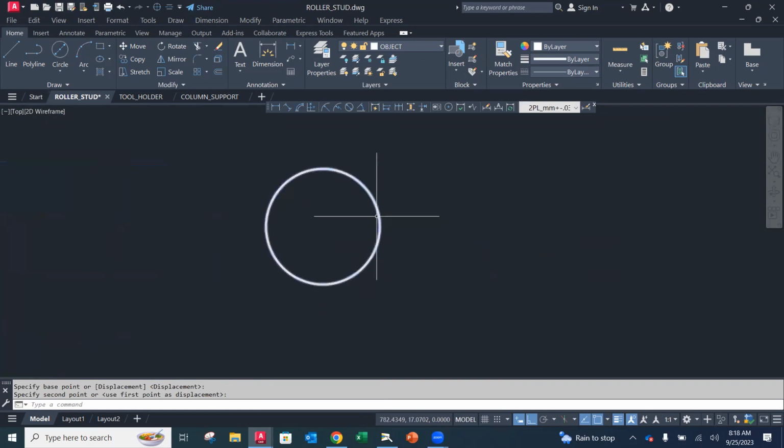There we go. Okay, then the diameter that shares this very same center is that next largest diameter. So I'm going to do a center diameter again, and I'm going to grab the same center point. So make sure that you grab the same center so they share the same center. And if you happen to be on the 0, 0, you can just key in 0, 0. And this one is going to be the 44.41.